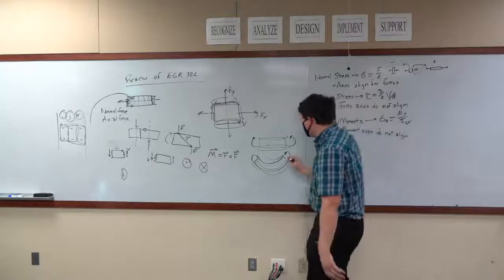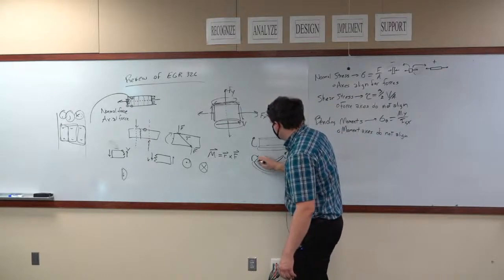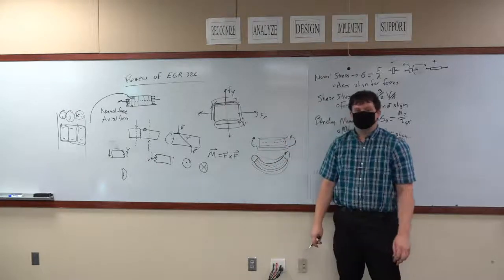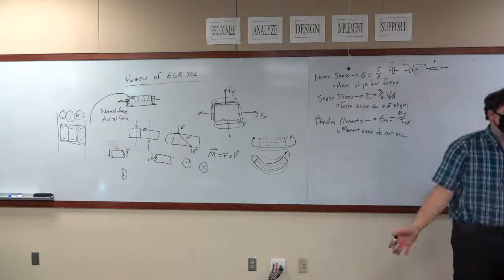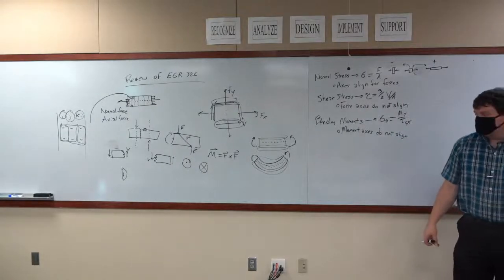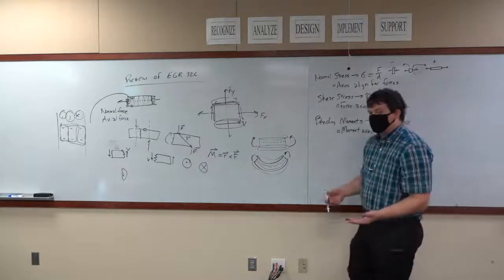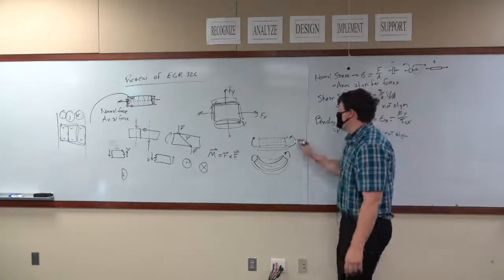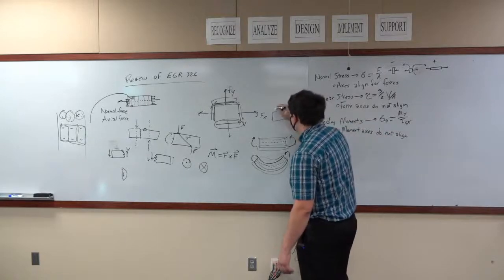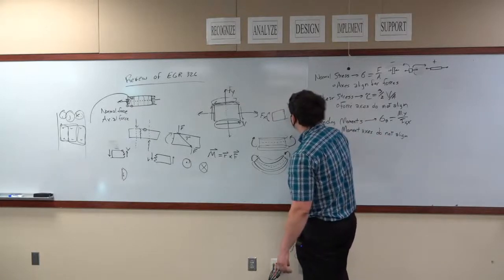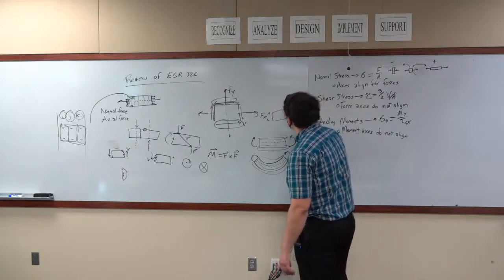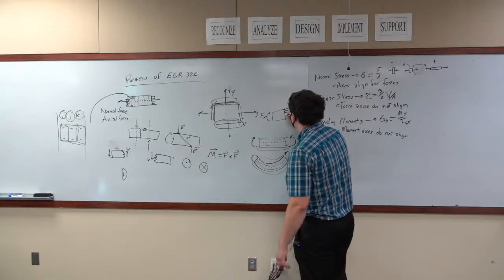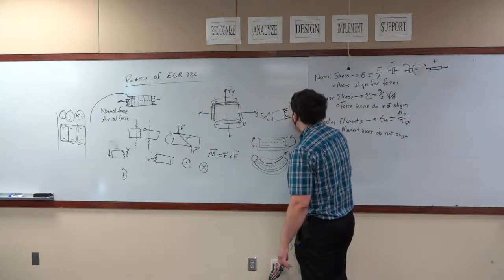And at some point in the middle, this line is the same length as this line, meaning it's not in tension or compression. So the bending moment creates a weird stress distribution on that cross section. If we break this cross section, what you end up seeing is, applying this moment, applying this back moment, at the top it's in compression, and at the bottom it's in tension.